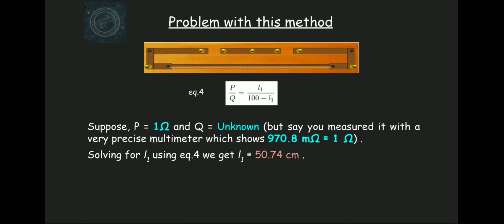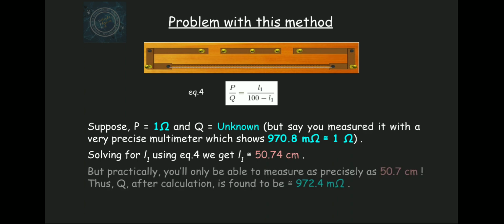So let me just think that I have a meter scale which has 50.7 and then it has 50.8. So while getting this null point, it will come slightly towards left in 50.7 and slightly towards right in 50.8. It will try to get a null point between 50.7 and 50.8, but you will not be able to measure the value because the scale does not have the reading. So you might want to take 50.7 as the null point, right? Although we never do a practical just once, we do it statistically many times, but let's just forget this.